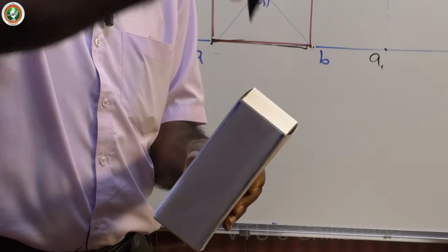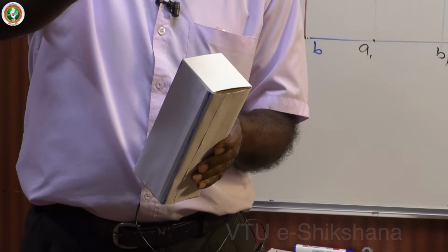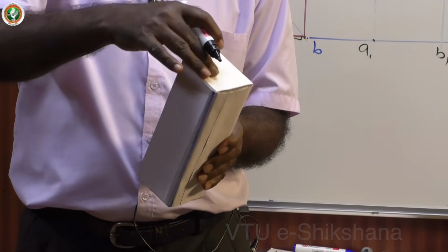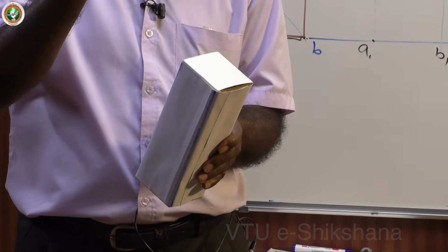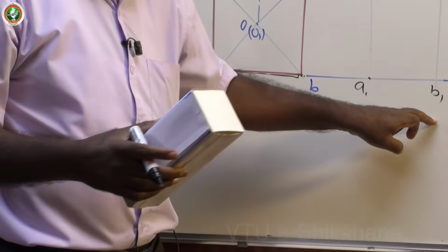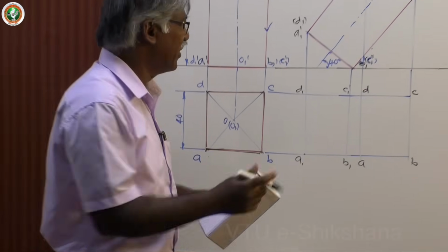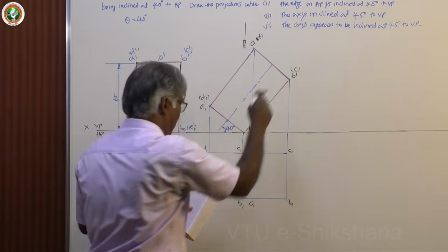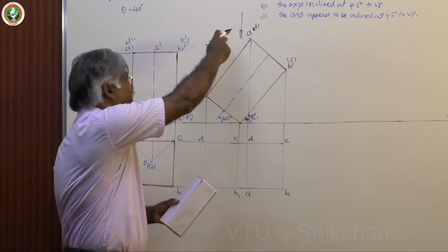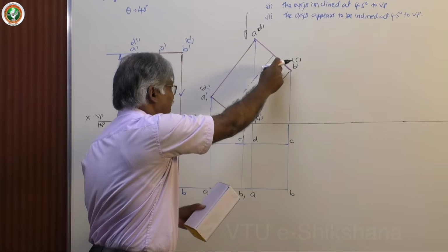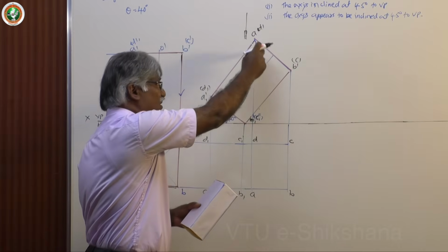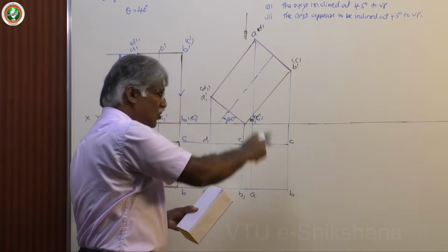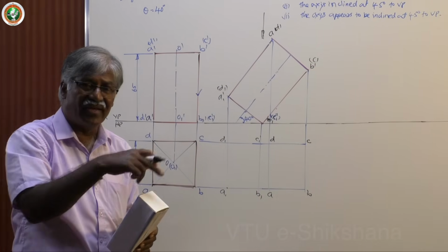Now, if you look from the top, the top face is visible. This is the only criterion I need to complete the entire figure. I don't need anything else. Just observe. I am looking from this direction, which is the nearest point to you. With the observer position, the nearest key surface is the top face, not the base. So, dark all the visible key surface.